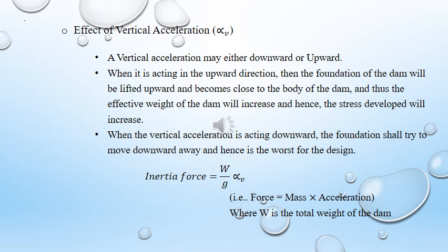So, the inertia force is the mass into acceleration. The acceleration in the vertical direction is due to the earthquake, and the mass is the weight by gravity.